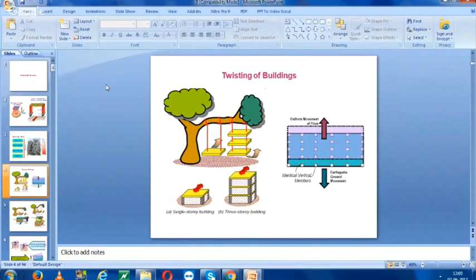Again, if we talk of this type of energy transfer and translational motion, we need to keep the configuration of the buildings very well planned. You need to keep the stiffness the same throughout the building. You can't increase or decrease the stiffness abruptly. The same is the case with mass. You can't increase or decrease the mass abruptly. You have to keep consistency from the foundation level to the top floor level. If you are providing a particular stiffness, slab thickness and column sizes, consistency should be maintained from top to bottom.